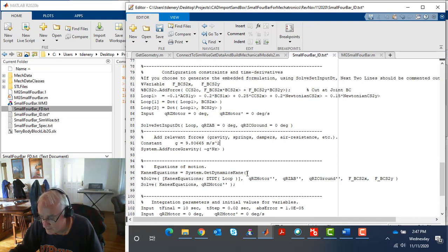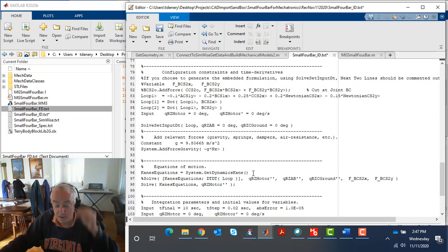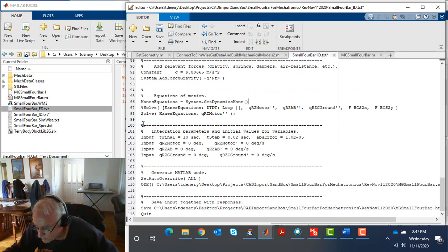But at this point, it's all kinematics and motion description. We put in a gravity definition, and it's only once we create our system of equations for mechanical dynamics, which we're going to call Kane's equations, that we really bring F into it. And it's here that we take our very carefully defined structure that will dictate the kinematics available, but we set that, which I'd say implies A, the acceleration of any point on any one of these bodies. But it's only when we get the system of equations that we start attaching it to the forces that drive the system.